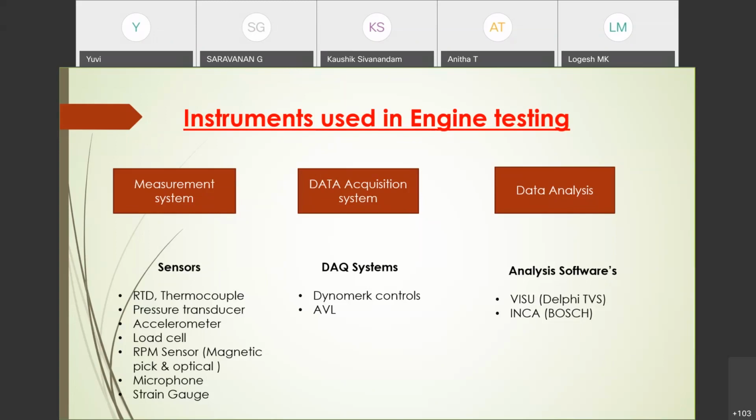What do you mean by data acquisition system? I can say it's a device to store the data and view the data as well. Let me tell you the basic block diagram of a data acquisition system. We have a transducer. The output of the transducer is sent to the signal conditioning unit. From the signal conditioning unit, it goes to the multiplexer. From there, it goes to the analog to digital converter. Finally, you can view the data on the display.